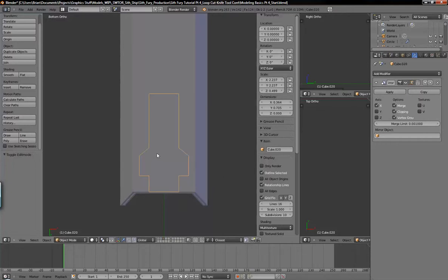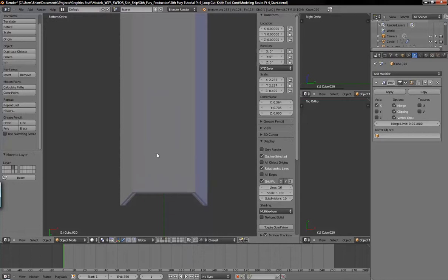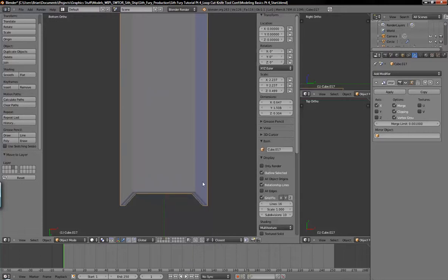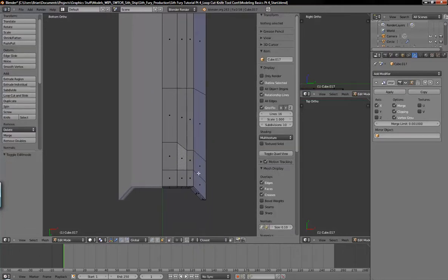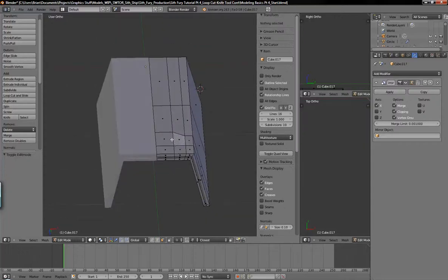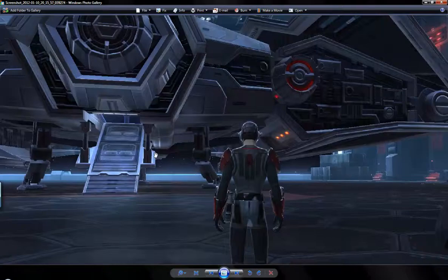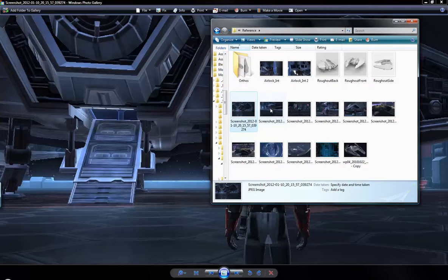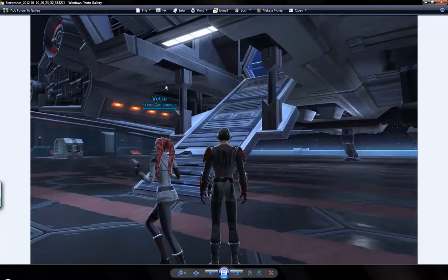So we're going to move this out of the way, hit M and then 4 to get it to layer 4, then right click on this guy again and tab into edit mode. And now we want to delete, I'm going to get a better view here. Let's see, that one should do.